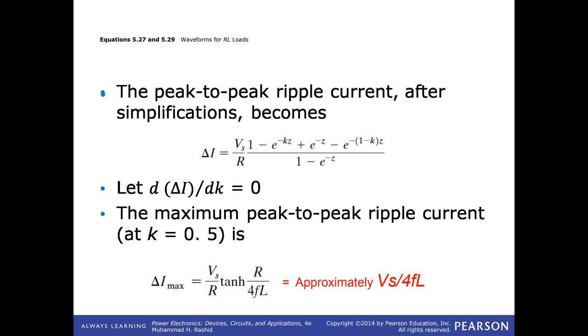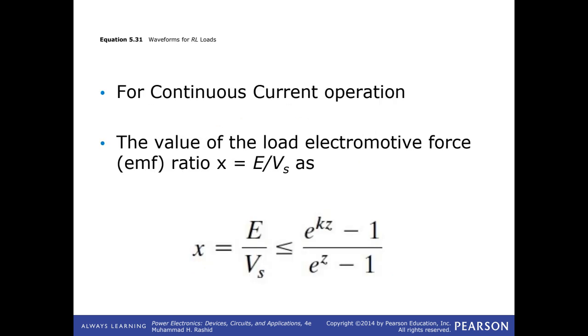And this equation, the red one, the approximation, is useful. It reflects how important it is to increase the inductance value, which obviously means volume and money cost, and how good increasing the frequency would be in order to reduce the current variations.